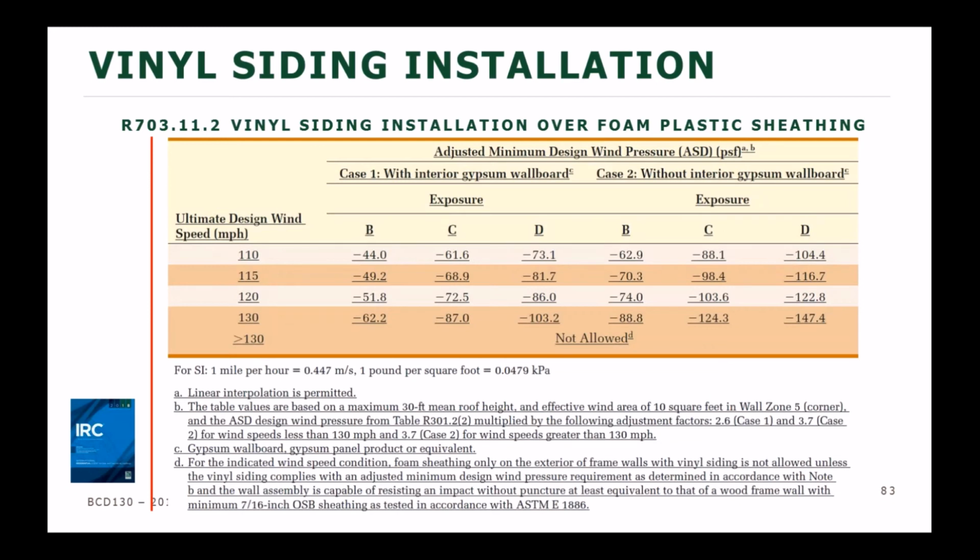So that was kind of a change that we saw coming in with the 18 codes, is some instances where vinyl siding could meet the testing requirements and meet these very high wind pressures, then it could be allowed to simply be nailed more frequently into the wall sheathing and not have to be nailed specifically into the studs behind it. So just trying to allow yet another opportunity to install things without looking for where the studs are.